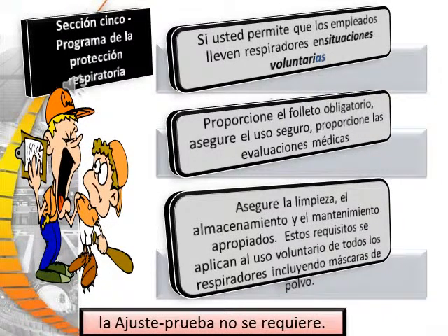If you allow employees to wear respirators in voluntary situations, they must be provided with a mandatory handout to ensure safe use, and provided medical evaluations. You must ensure that proper cleaning, storage, and maintenance occurs, and these requirements apply to voluntary use of respirators. Fit testing is not required in voluntary situations.